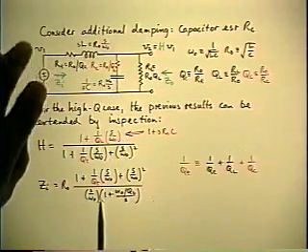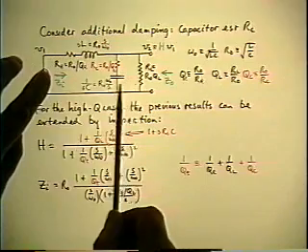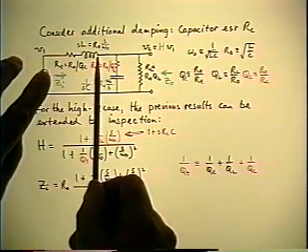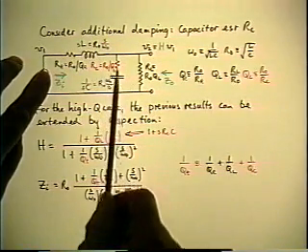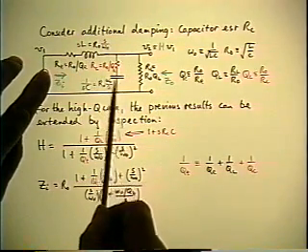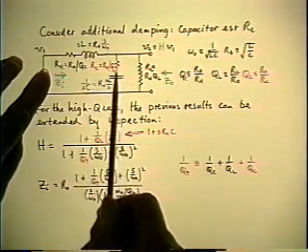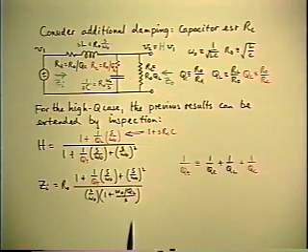No additional inverted pole or zero. Go to infinite frequency. The input impedance is dominated by the inductor. The capacitor goes to zero, and whether you're left with an RC or not, in series with an inductive reactance that's going to infinity, again the RC makes no difference. So there's no additional normal pole or zero.